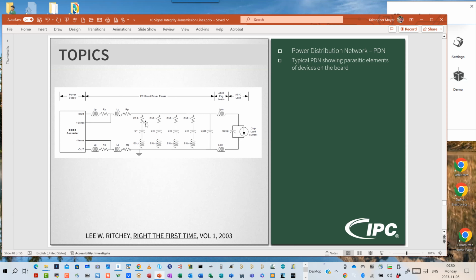And then for every physical capacitor we put on our board, whether that's a tantalum or some ceramics right here, for every physical capacitor, I get a free resistor, free inductor. Then on my IC chip, the device that actually needs this power, I have input capacitance right here on the input pin, and then both my power pin and my return pin also have lead inductance right here. You'll notice the only device that shows no resistance, no inductance is the PCB itself.